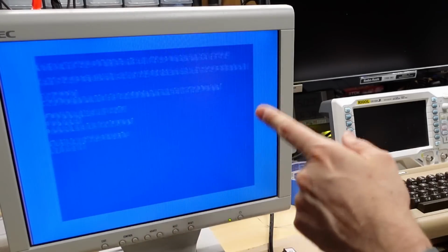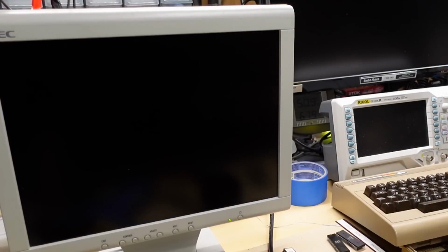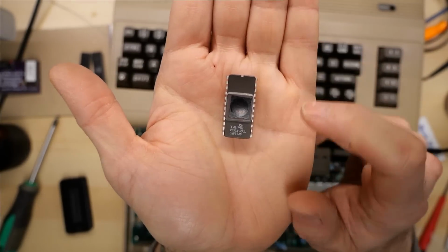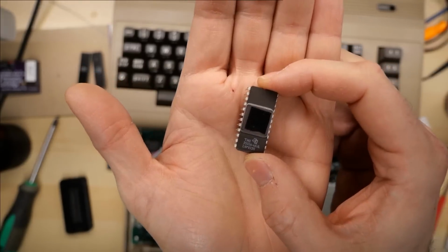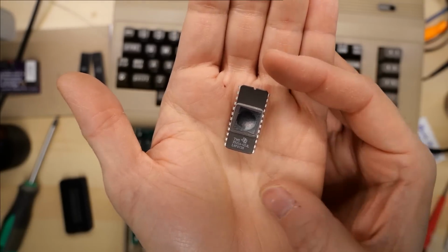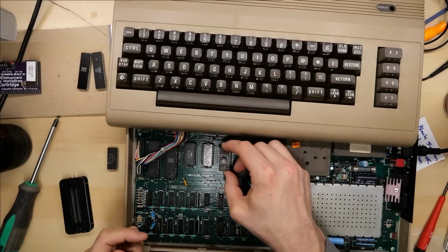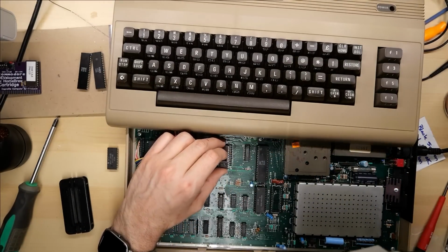So I'm going to pop in the one from the ZIF64, which has the skinny character fonts. In case you're wondering how I installed a different font in the Commodore 64, I used a TMS 2532A EEPROM. Now these are hard to program. You can't just program these on a TL866. I had to use my Data I/O, but with this, it does just plug straight into the Commodore 64, and you can put any font you want on it, so I loaded the VIC-20 font.